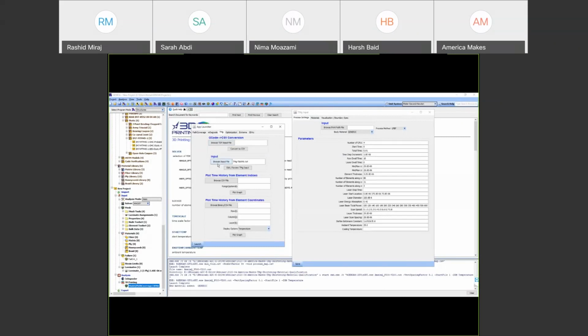So TMG input on the right, there. So we have three tabs. One is process settings, materials, and visualization, as my colleague mentioned. And here we have different parameters from down there. And, you know, you can change, for example, you have power and scan speed, and you can define different range. On the top right, you see the process methods that we already have available in TMG, such as the laser powder bed fusion, SLM, and other processes.